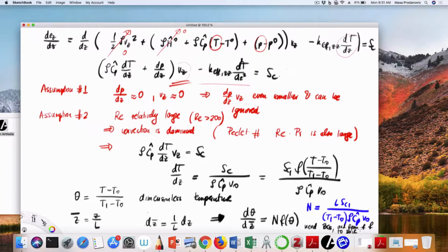So K effective is something that is fitted to the size of the particles, the heat capacity of the system, and the velocity that is going through, okay? So I'm assuming I have that term. There are some formulas that can help with evaluating it, but overall it's possibly something that depends on Vz. In which case this can get complicated, right? So I would then get a different solution, and then I have to deal with the second order equation. And possibly numerical software is the way to go.